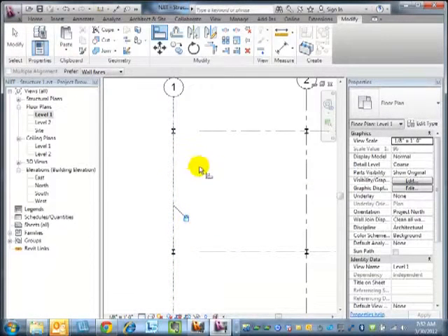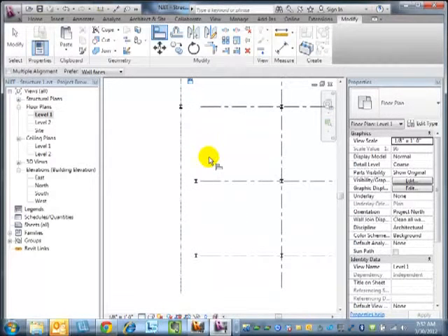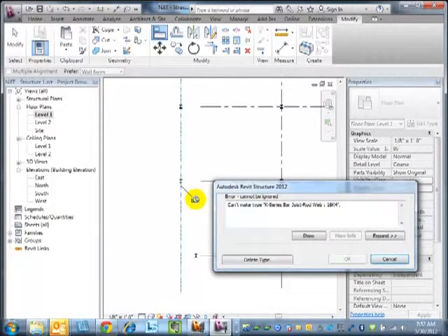Although for the purpose of the intersection, you may be very right that it's not generating. The grid lines are theoretically infinite, but you can give them a bound too. So I think if the intersection was outside the bound of what they're currently defined to be, it wasn't doing it. What I'm doing here is just reassociating those columns with the grid. Use the align tool, and then lock things into place.